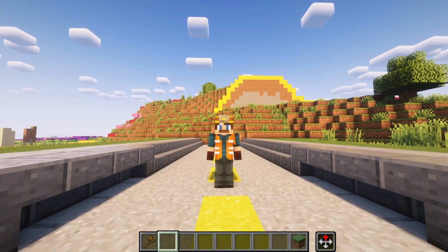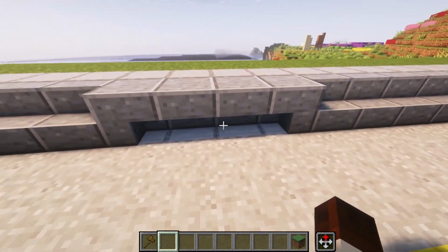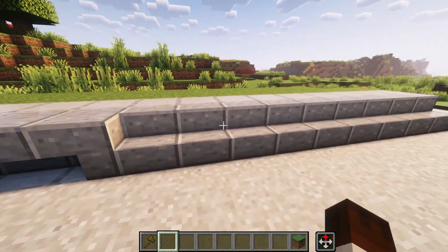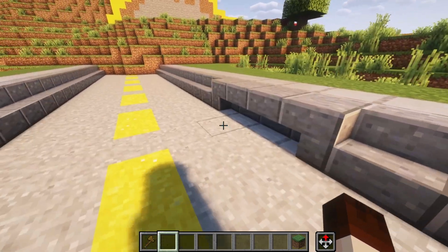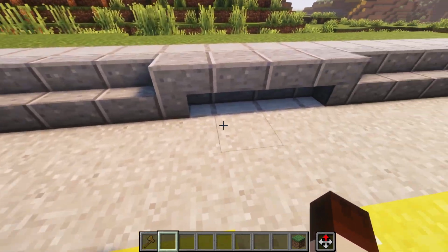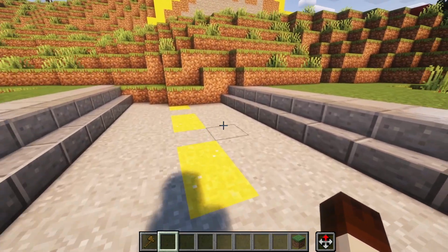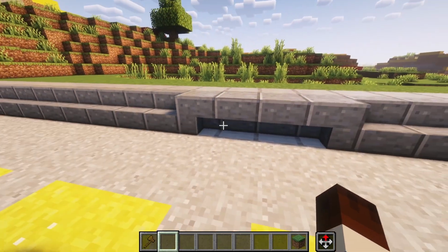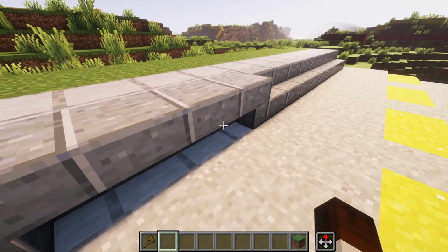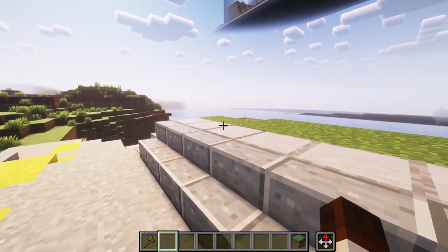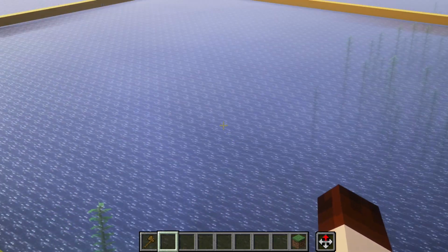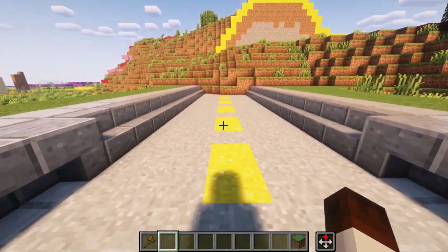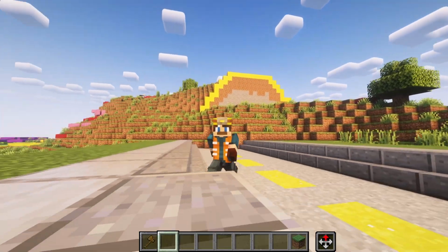And you can see to my left and right here a couple of curb gutters in our road. Often you'll see driving down the road, you'll have these little slits along your curb, which is the barrier from the road to the sidewalk. This is where stormwater is collected from roadworks. Often water is running transversely along the roadway and enters these systems, where it is then carried out through some sort of network and either down into a tributary water source like a pond, lake, or river, or into a stormwater detention or retention pond that we'll get to later.